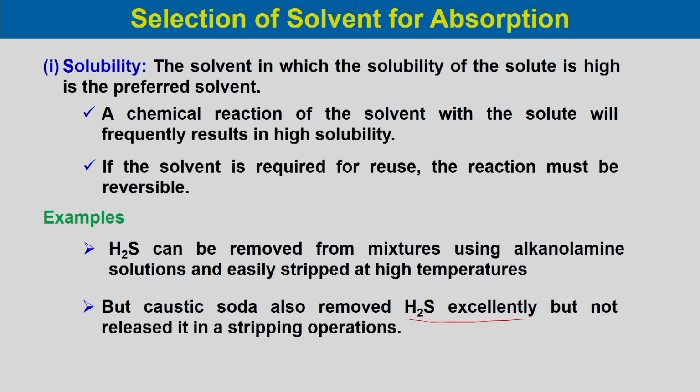But if we do not want to strip it back, we want to make a solution of it, like caustic soda, it also removes hydrogen sulfide excellently, because it is a very highly alkaline, basic solution. But it does not release the H2S in the stripping operation, even if we increase the temperature, because the reaction is irreversible in nature.